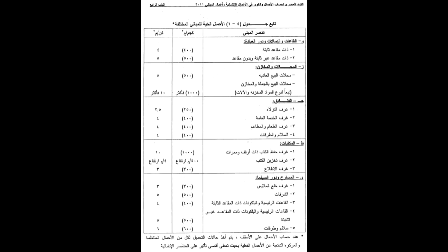For school and university buildings, the classroom 300 kilogram per square meter, the labs 400 kilogram per square meter or more, depends on the equipment also. Sports halls 500 kilogram per square meter. Rooms for storing books, having shelves, and the corridors 1000 kilogram per square meter.